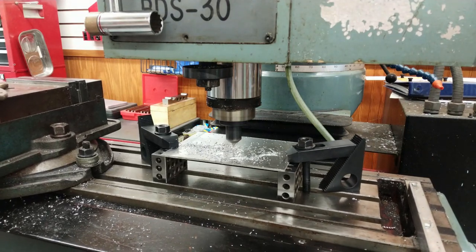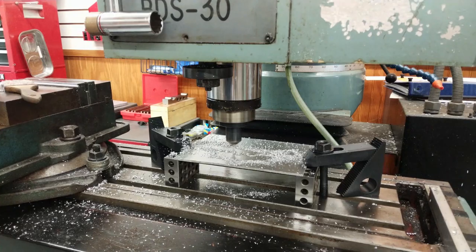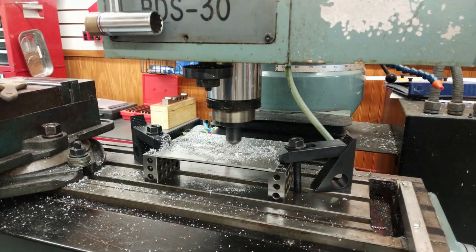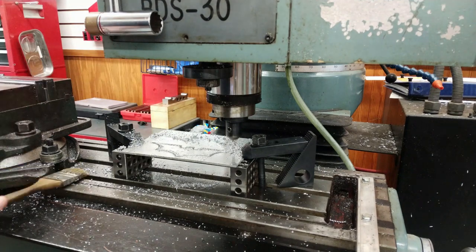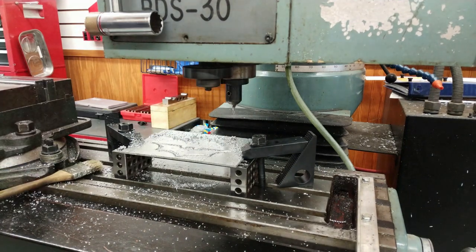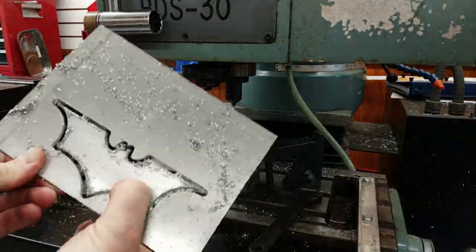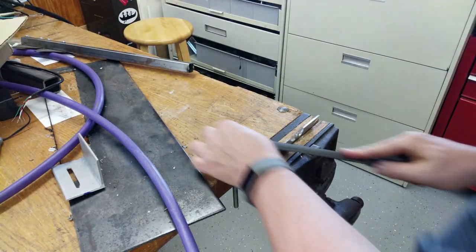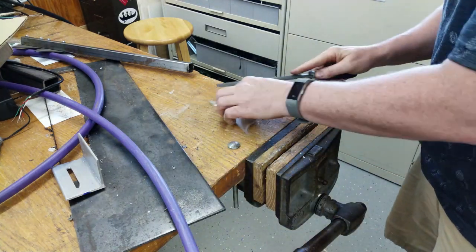You'll see that I'm using a little bit of lubricant. This tiny little 1/8 inch cutter clogs up with the cutting chips really easily, and I broke a cutter on my first attempt. So I'm just using a little lubricant to keep things clear and brushing out from time to time with a brush. When the part comes out, you'll see that the holding tabs are just big enough to keep the piece in place, and the part easily breaks out by hand.